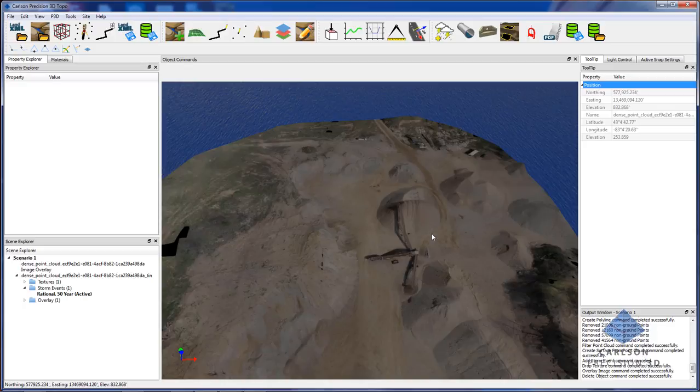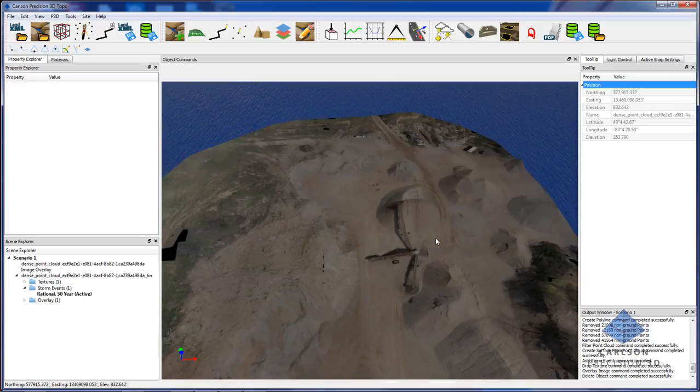And again, if you apply a filter and it takes out too many points or gives you a bad result, you can always hit Control Z even during the command, and it'll undo the last filter. And then you could tweak your settings, and then you can reapply the filter at that point until you're satisfied with the results. So there you go, advanced Bareground filtering on unclassified LAS data using Polygon boundaries.